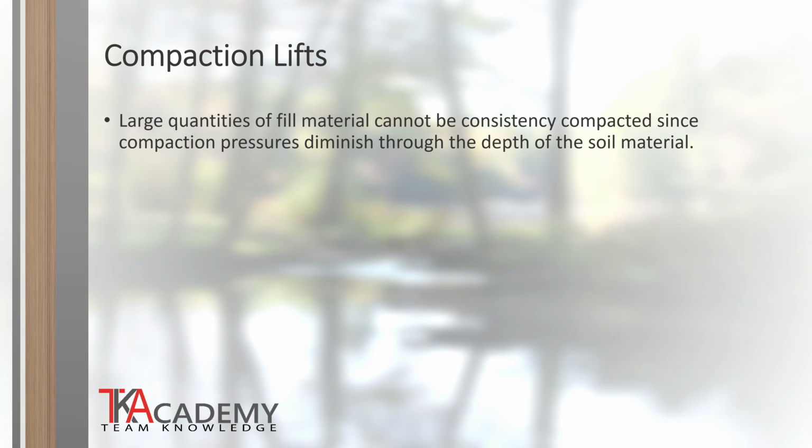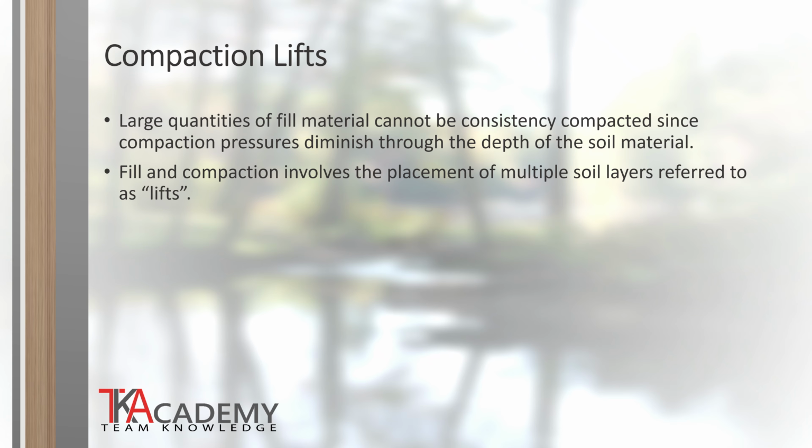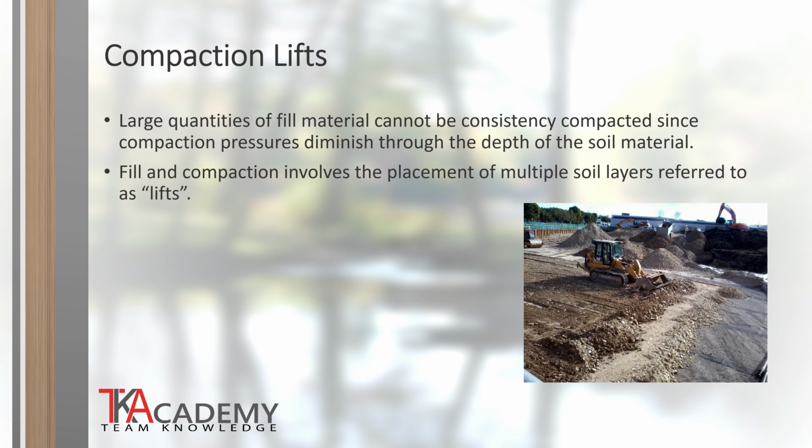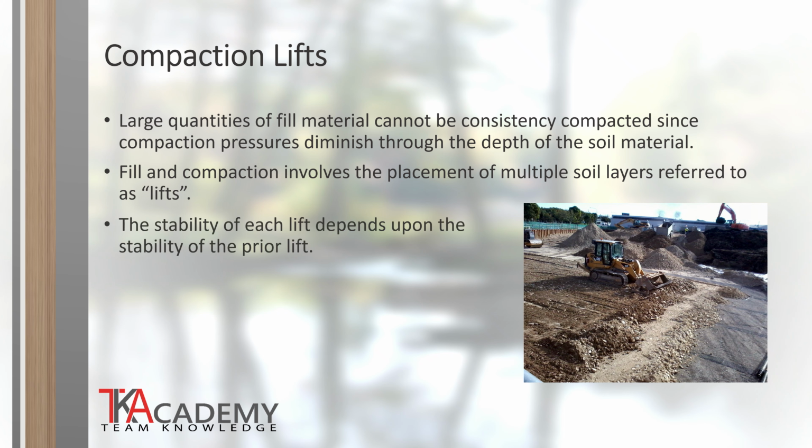When placing fill material on a site, it cannot be done all at one time, otherwise it will be unstable. Even with compacting the top of the fill, the compaction pressures diminish through the depth of the soil material, so the lower areas will not reach the compaction level needed and settlement will occur over time. The proper technique for building up a site is to do it in a series of 6 to 12 inch layers called lifts. The site is built up in lifts because the stability of each layer depends upon the stability of the prior lift.